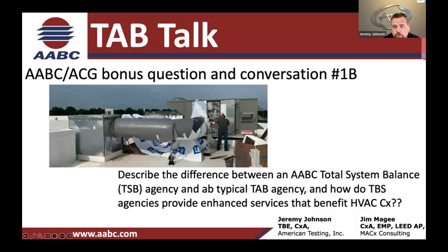And that falls into the readiness checklist, where you can go through with the contractor. Hey, if all my dampers are 100% open and I'm not reading any airflow, ding, ding, ding, warning, we got a problem here. We're not balancing this until you get this resolved, right? Presumably you want the boxes, the terminal units under control. That's where you really go into a steady state that you can have success balancing if a lot of those things are vetted out ahead of time, and the tab readiness checks gives you that ability to vet it out.